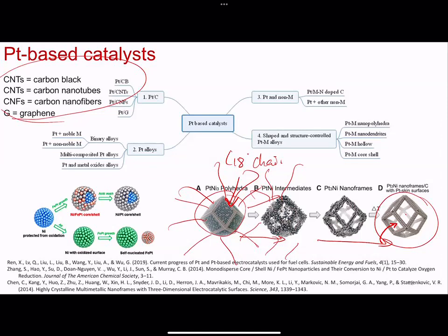There's also specialized carbon structures like nanotubes if you want directionality in electrical conduction. You can have carbon nanofibers, you can have graphene. I mean, the flavor of carbon is really up for grabs, and it's your choice. But the cheapest is just carbon black. As long as there's enough carbon, you will have a percolated network, and there will be electrical conductivity. It also spreads out the platinum so that they don't agglomerate. But this is also a huge area of research.